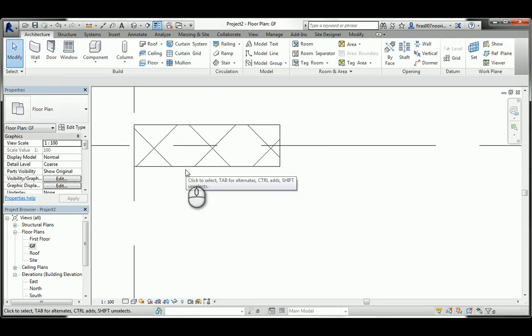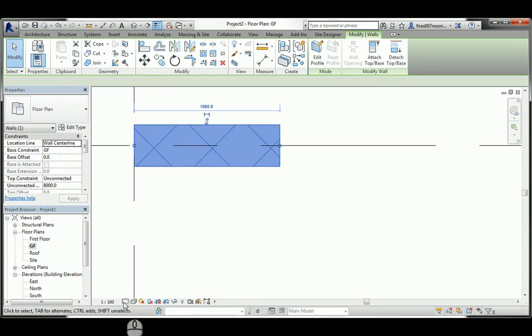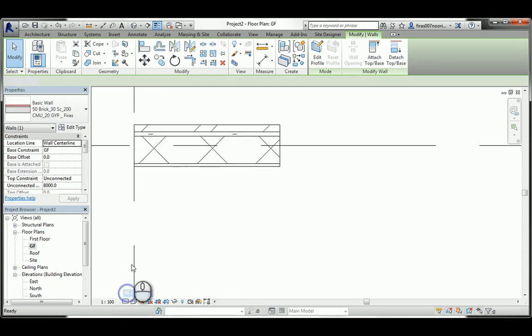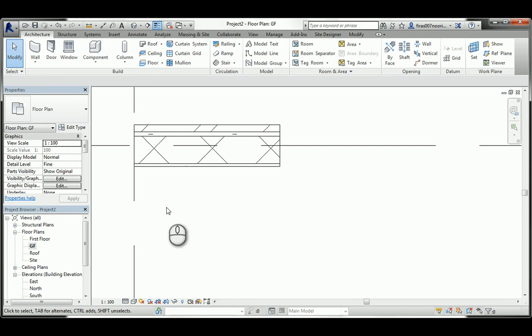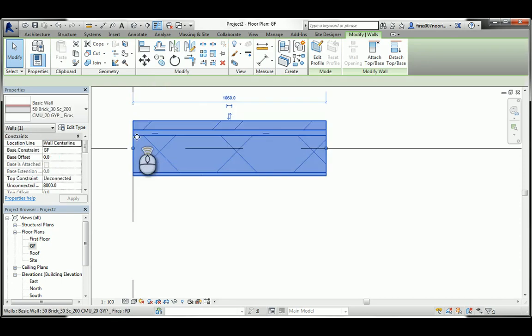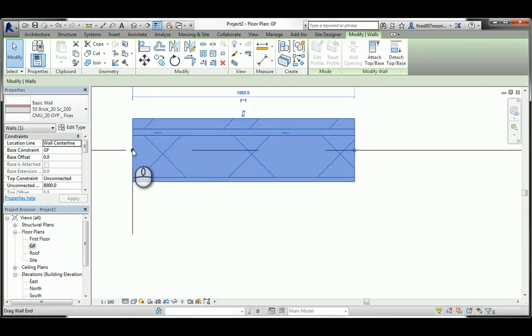So in order to see things in a better way, you must select this one and go to Fine, allowing Revit to show you what has actually been created as complex materials. And see the scary thing. See that this is the wall, and this point is the wall center line. While this is not really correct, we should create and place the wall based on its core center line, which is specifically here in the mid distance between the core end and the core start.